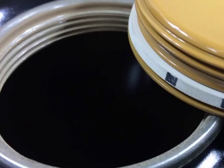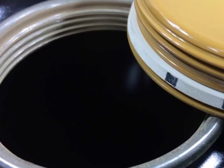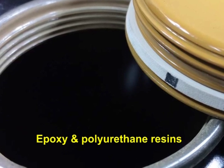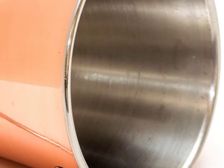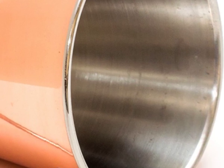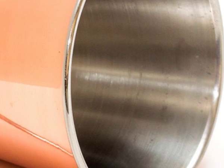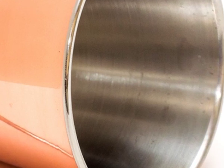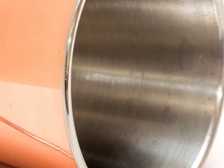The inner surfaces of drums and pails are usually treated, epoxy and polyurethane resins being the most common. Instead of applying the lacquer to the base sheet, it can be sprayed inside the drum after fabrication, to ensure that all seams are adequately protected.